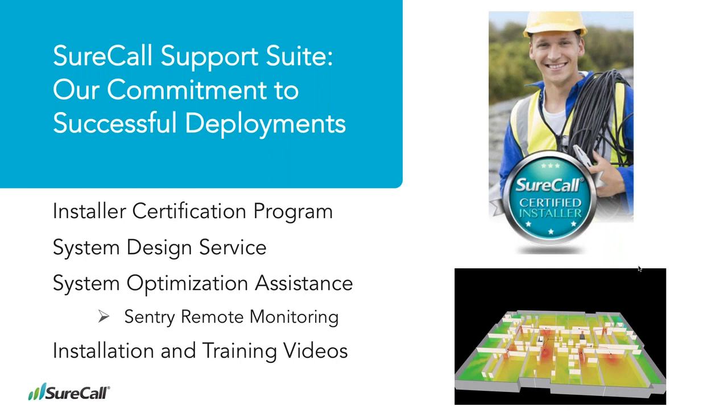Right. While you were redialing in, I was explaining, you had a picture earlier of an office building. It's a two-story office building with an all-glass front. You may think that would have great signal coming in from the outside, but in reality, if you've got low-E glass, which a lot of buildings do now, then the signal inside those windows is actually pretty poor.